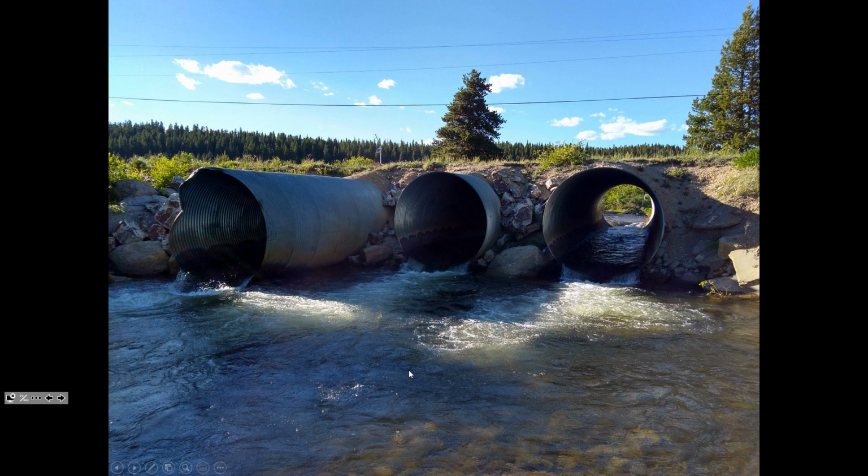So that's something that when we get into HY-8, you have to pay careful attention to, is the geometry of where everything is. You're telling the program the diameter of the pipe, how long the pipe is, but you're also telling it, for example, what is the elevation of the bottom of this compared to the elevation of the river that's downstream. Sometimes you just set the pipe right on the bottom of the river and build up around it.